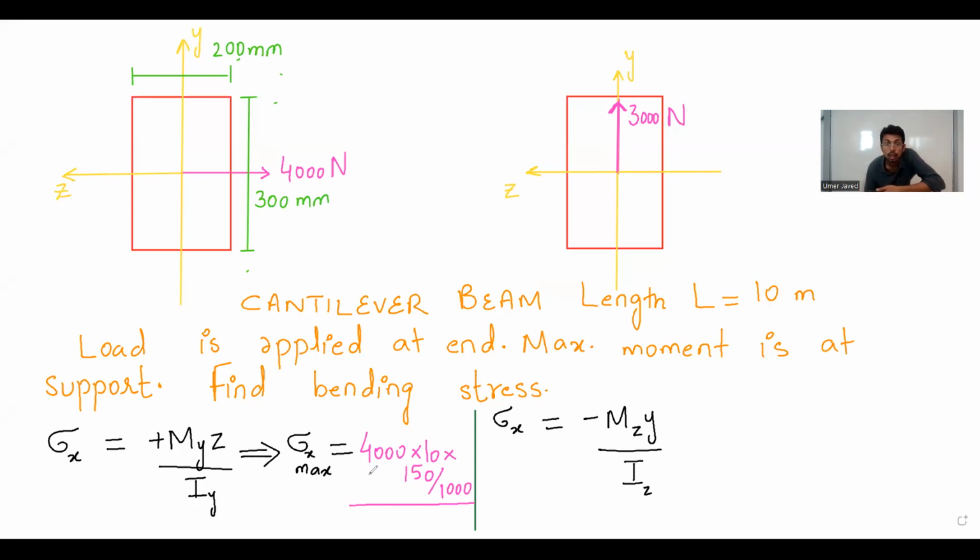I'm just talking about pure bending of beams that we already have covered. There is just one more thing that I want to add, but right now let me just complete this example. You can see that there are two different cases. On the left you have case A. I'm using the simple bending formula Mz over I, and I'm trying to find the pure bending stress, the maximum bending stress. So you can see that I'm writing this formula.